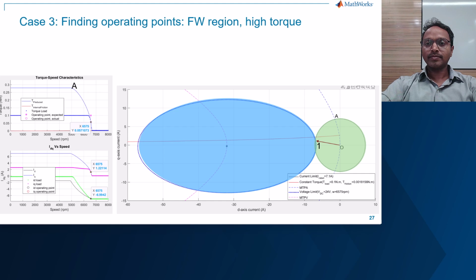We know that when the torque reduces, the constant torque curve shifts downwards. We can reduce the possible torque value till such a level that the constant torque curve of the reduced torque intersects the overlapping region of current limit circle and voltage limit curve. Such maximum supported torque curve goes through the point 1 of the intersection area of the figure. This curve represents the maximum system current being used, as shown by the gray circle.